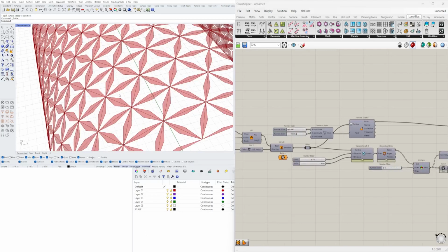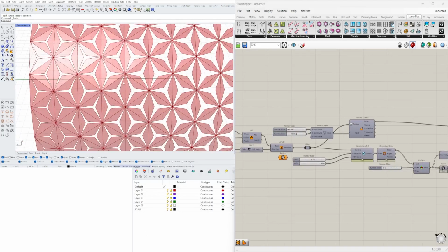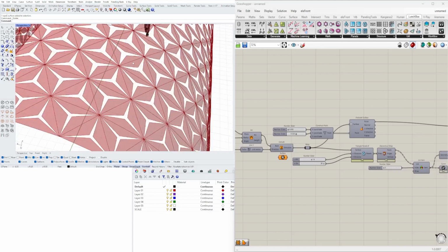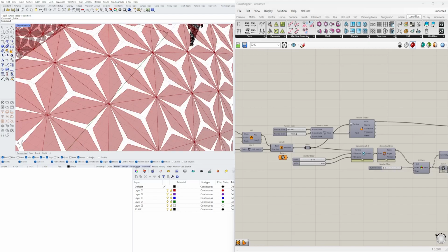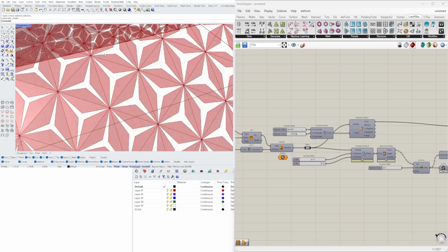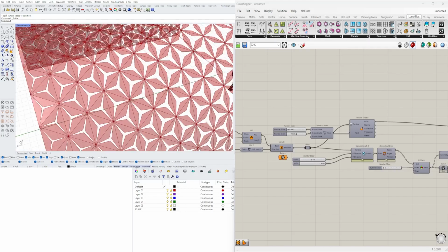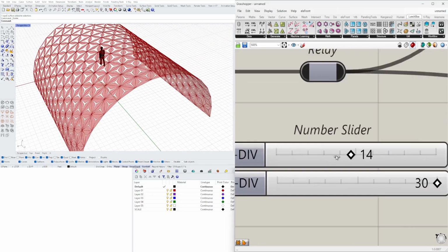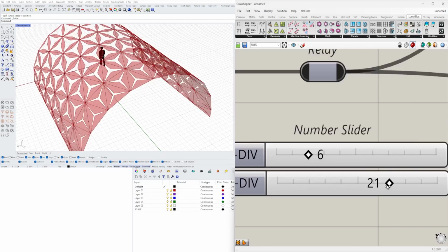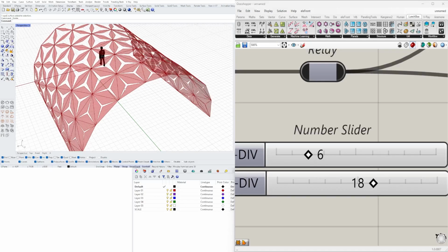So what I mean by making it more functional is this would be really hard to develop because they're just planes. So what we need to do is offset the original surface and create a wireframe, and then have this pattern be within the wireframe. So the first thing I'll do is decrease the number of subdivisions to make it a little bit easier.